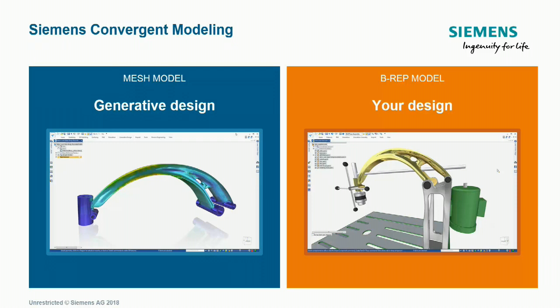As an example, on the left we have our generative design that created the mesh model, and we want to incorporate that into our existing design on the right. To do so, it requires a few little changes. It needs a counterbore hole because of the way it connects to the stand. A rod passes through it, so it needs a cutout for that penetration.